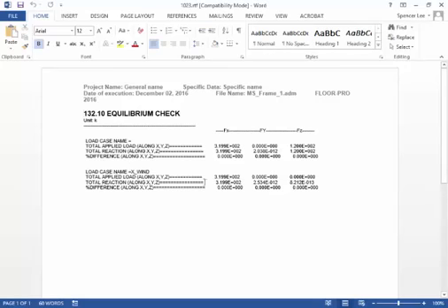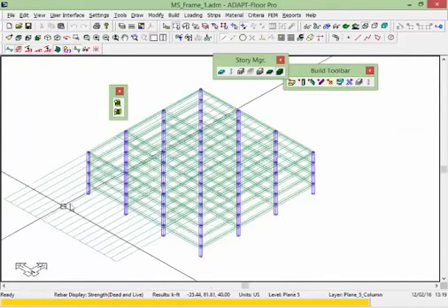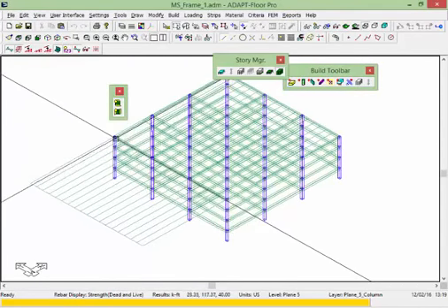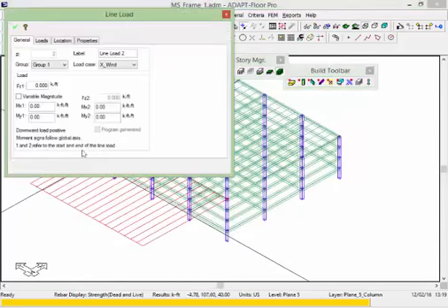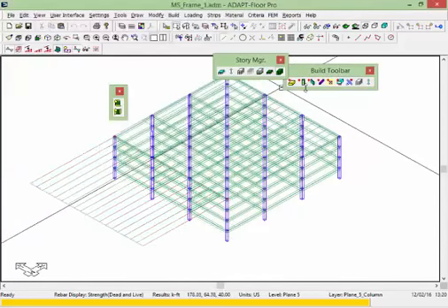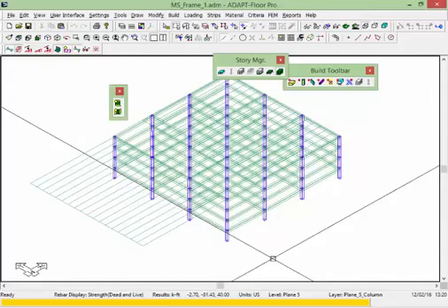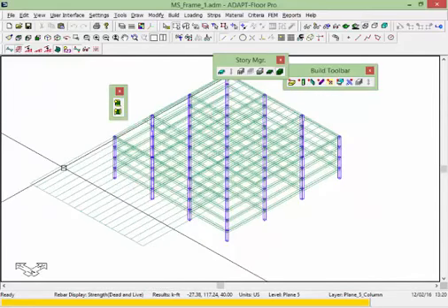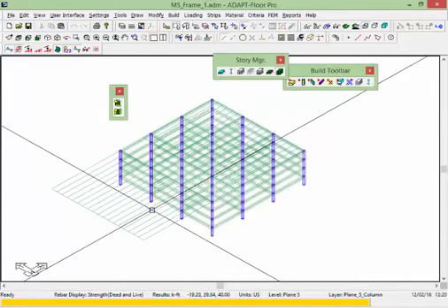Let's go back to the model and see what I have wrong. So this is 40, 40, 40. That's 120. Oh, that's where I'm wrong. So it's 120 plus 120. So that's 240 plus 4 times 20 plus 80. So 320. That's what I was off on. So I was only calculating for one bay. It should have been 3 bays. So that's in equilibrium. The applied loads equal the reacting values at the base.